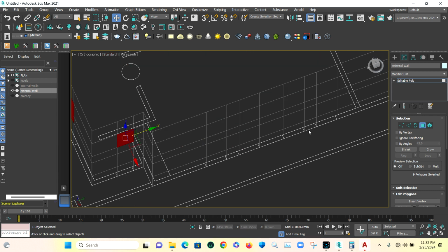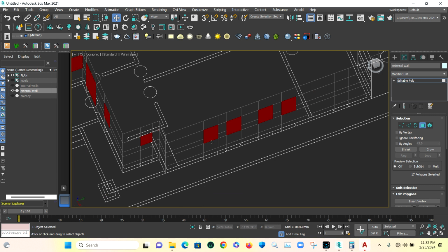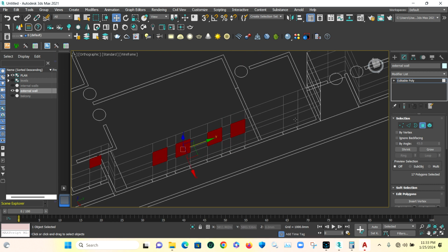Now I've selected this. Next are these windows. I hold my Control and I select them. Remember, it's left for me to choose the level of the window, where it starts and where it ends. For here, all of my windows stop at lintel. Remember, you can have situations where it does not stop at lintel. Then that particular level where it stops should be identified when you are assigning your levels, so that at this point you just select them. So you do this, you continue.